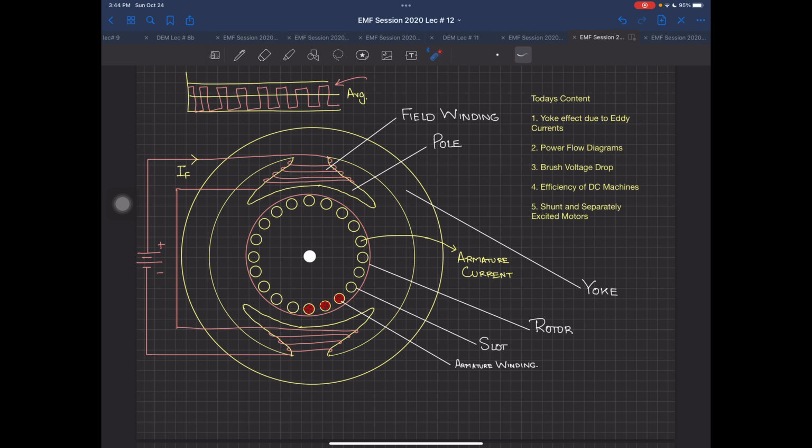Now the rotor, we know that it's always going to have an AC current induced in it, and because of the commutator action, this is going to be converted into DC, and then it's going to run on. So technically, eddy currents are always present inside the armature. So the armature is always going to be laminated. Why? Because it is going to have an AC current induced inside it, whether it's a motor or a generator, both cases. So eddy currents are always going to be there. So this lamination for the rotor is a must always.